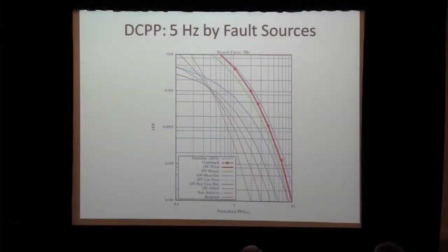So just starting off with a hazard curve plot, I'm going to be showing several hazard curve plots, and there are several things to first note that will be consistent for all my plots. The first thing is on the x-axis, this is now normalized PSA or normalized ground motion. The reason we're doing that is it's a little bit easier to see things when I normalize them because it shifts it to a range. But the more important thing is we're more concerned about relative changes. Because these are preliminary ground motion logic trees, we don't want to necessarily focus on what is the absolute ground motion at 10 to the minus 4, but we want to look at what is the relative change between one to the next.